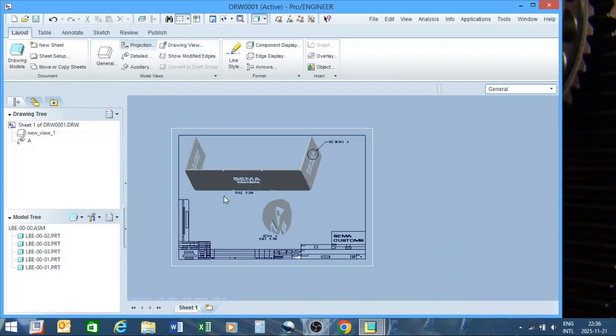Your projection view, this is now not going to end up in the block, but I can show you exactly how it works. We're going to go projection view. You're going to select the view you want to project. You can go to the side.